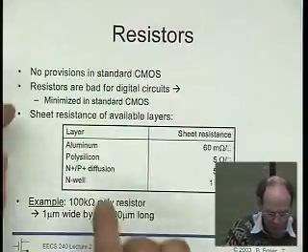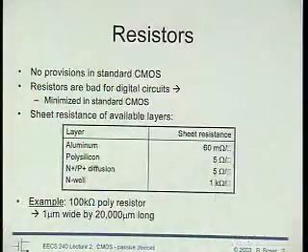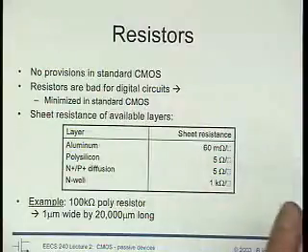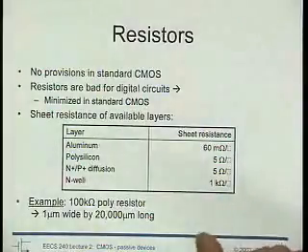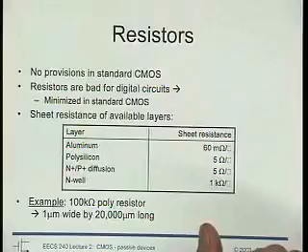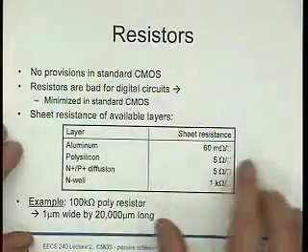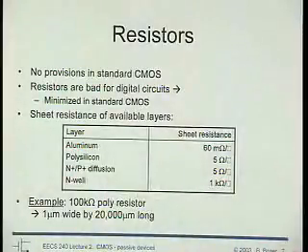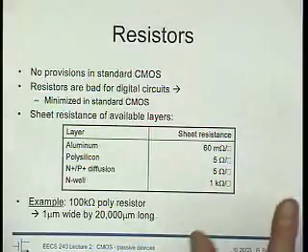And so now if you look at that, aluminum, of course, has a small sheet resistance, 60 milliohm per square. This per square business, everybody knows what it means. Okay. Polysilicon is a little bit more, 5 ohms per square. Diffusion also like 5 ohms per square.